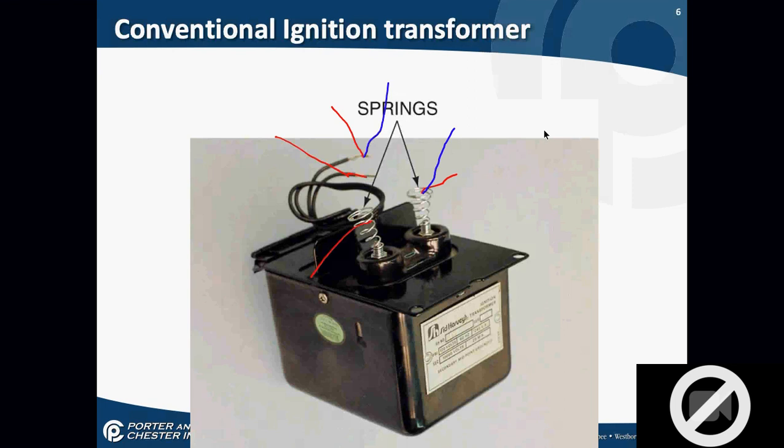Now, there's one more reading I want to take. Can anybody tell me what it is? The neutral? I've already dealt with neutral. The line 1 coming in? No, I dealt with that. What about if I wanted to take a reading from... Oh, ground. Yeah. I can have everything else okay, but I could have a short to ground. So if I put a lead on one of the screws, not a painted surface, and then to a spring of the transformer, or to one of the leads of the transformer.